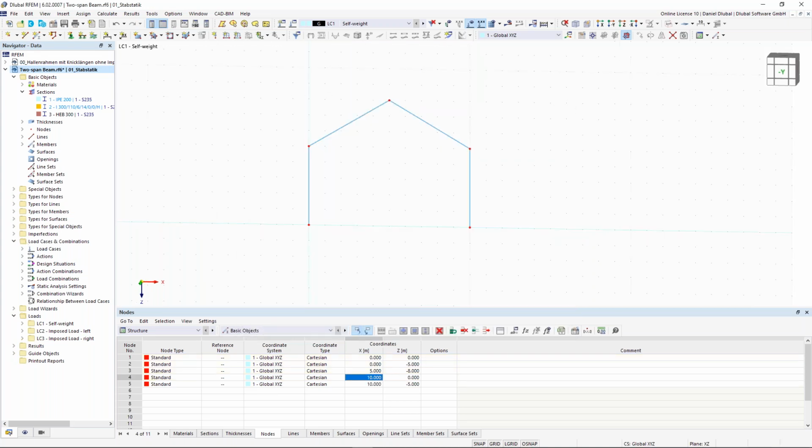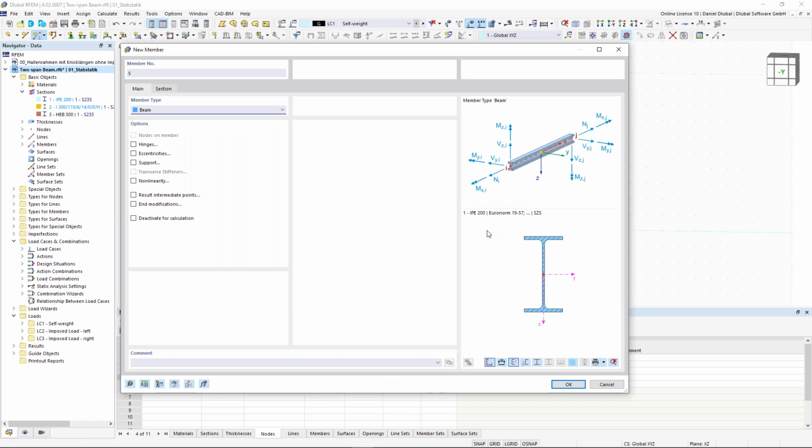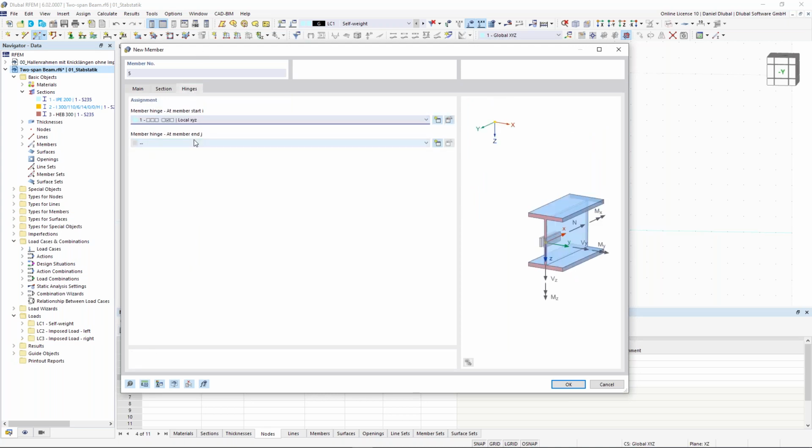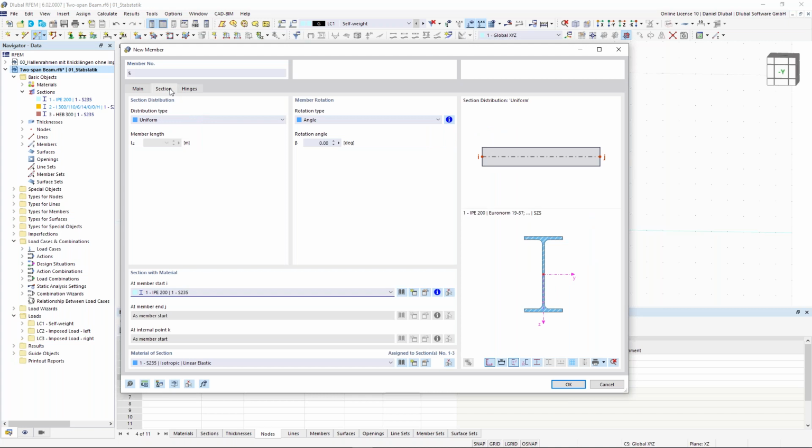Okay, the next thing is that we give them here an additional rod. And now we have different member types. You can see here we have the member type beam, and this member type transfers all internal forces to other beams. I can add to that beam additional hinges. Let's do it in that way, and then I will explain you other member types. So hinges, I say to them the phi y should be activated, so there we will have bending moment hinges.